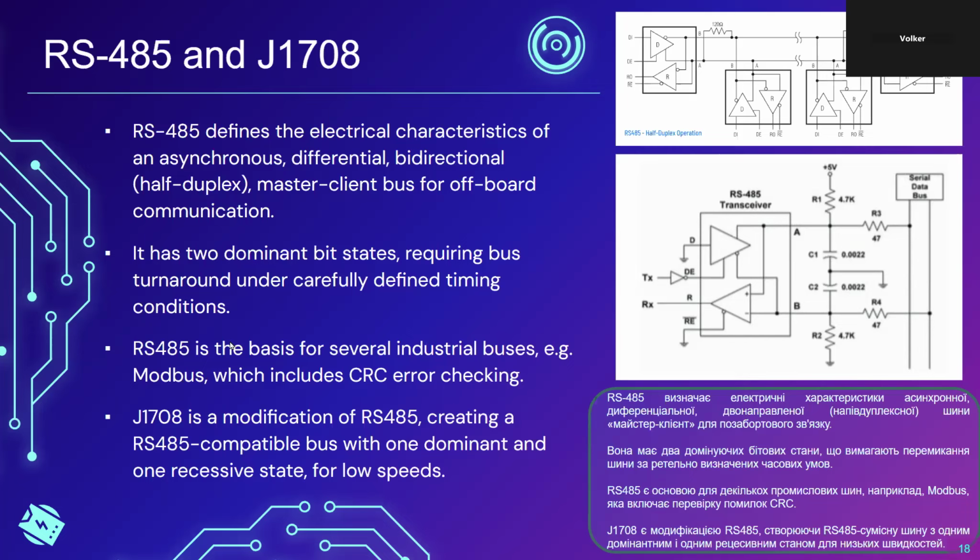Depending on the cabling that's being used, RS-485 can go up to 1.2 kilometers, 4,000 feet. And that is the more or less official specification. Really, if you drop down the speed, you can run RS-485 for kilometers. If you drop down the speed, then you can also run RS-485 on less than ideal cabling. And that makes it useful.